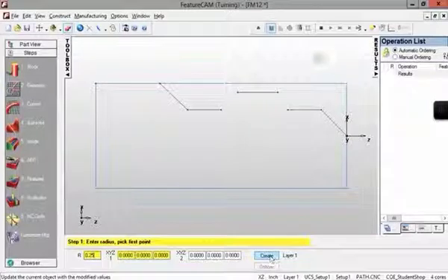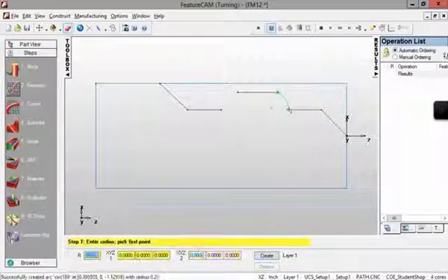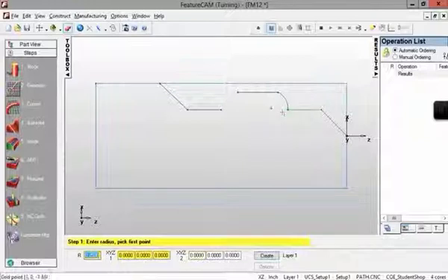And then you don't need to click the create button. You just select the points. So select point 1 and point 2. And you may already notice that this arc is not in the right direction. So we want to flip this arc. The way we flip this arc is to push this option button. But it's gray here. We will do that later. Let's finish the drawing of the other arc. And then, okay, when we push the escape button, we end this arc drawing mode. And let's select this arc, push the option button. See, it's flipped now.